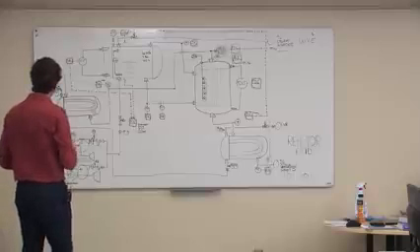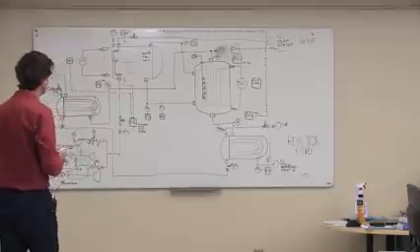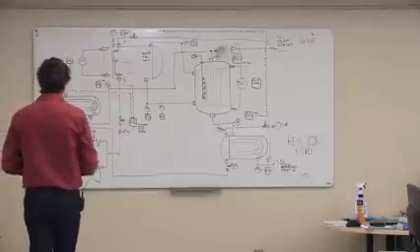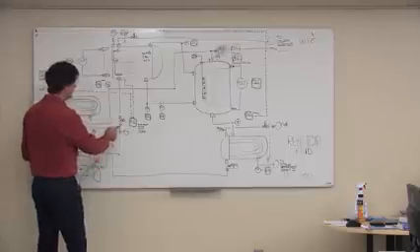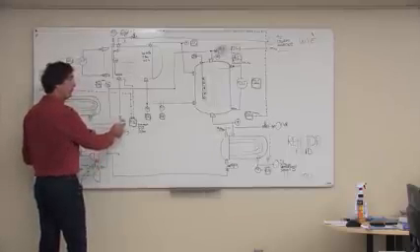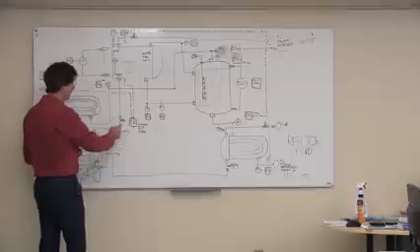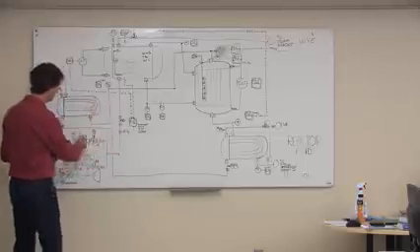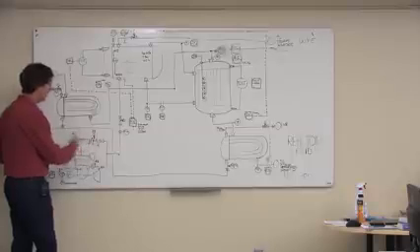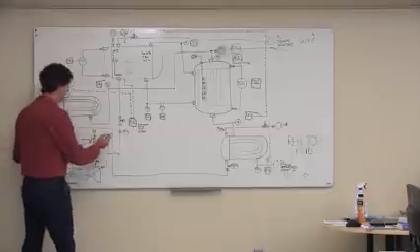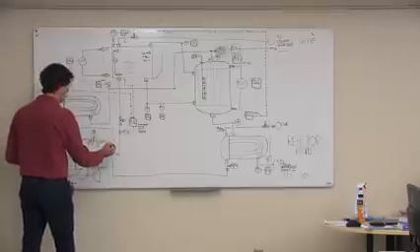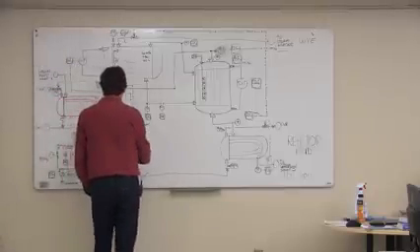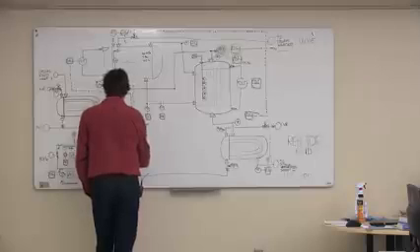The only thing maybe now to add is some safety systems here. If you've been listening to me talk the last couple of days, if that valve for some reason fails closed on us, we need to have a way to send that water back to its supply system so that we don't deadhead the pump. We don't want the pump just turning and putting power into that water and heating the water up. We want to send a small flow back. So we need to put what's known as a minimum flow bypass.